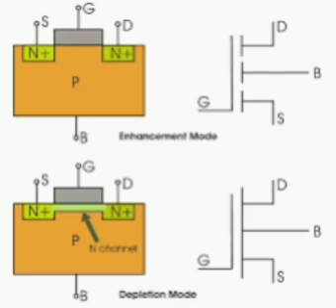Solar cell is operated in the fourth quadrant. The product VI is negative, which implies that the solar cell is acting as a source of energy. ISC equals -IL equals -qGLA(W + Ln + Lp). VOC equals ηVt ln(1 + IL/I0).